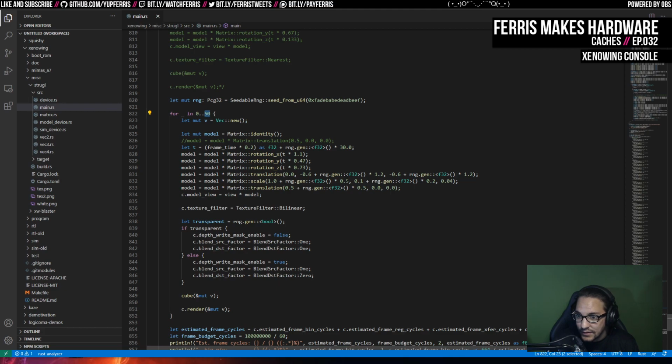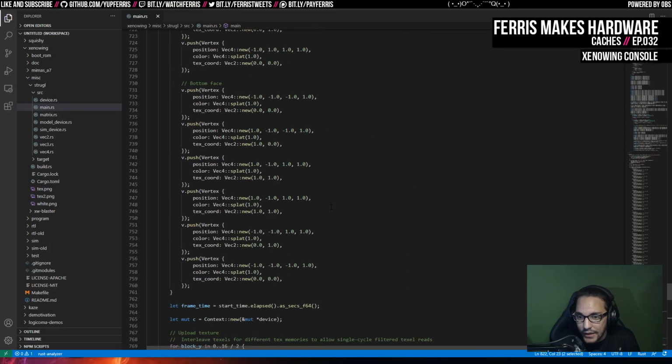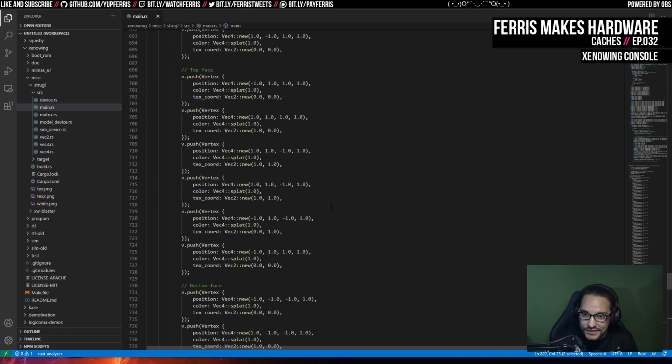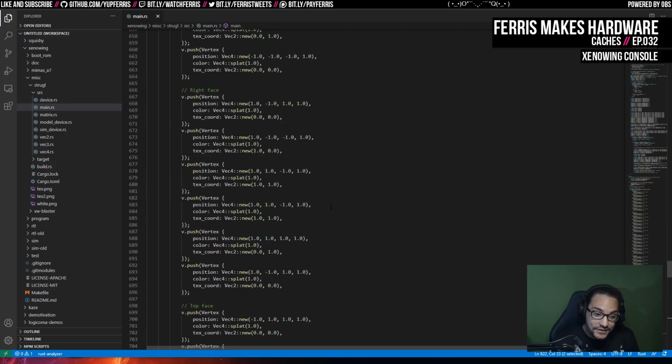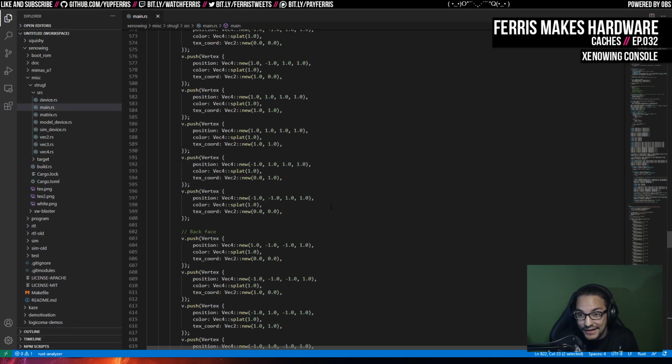And the video output itself will be 640 by 480 because that's going to be the actual resolution that the hardware outputs, and then it'll just use scan doubling when it's less than that. And I think a lot of consoles of this era actually made that configurable too. So maybe I'll do that. And then you just take a performance hit in the cases where you're using 640 by 480. But the cool thing is it'll never interrupt the actual video signal. It'll just change whether or not scan doubling is done and how those caches work. And of course, the amount of data that you need to pull out of cache.